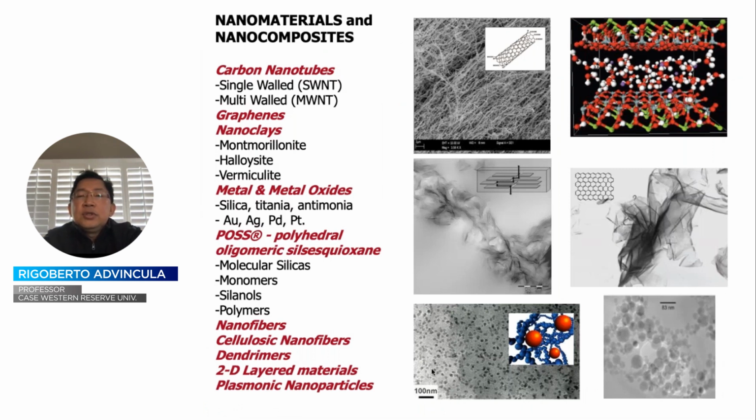So with that, I would like to use the rest of my time to focus on nanomaterials and how we've used this together with SLA 3D printing. Nanomaterials represent an added dimension for controlling the thermomechanical properties by using filler materials. And as you can see here, the nanofiller materials comprise clay, nanoclay, nanofibers, cellulosic nanofibers, and then graphene. A lot of these are commercially available, and many companies are very interested in using these nanofillers to further enhance the properties not only of SLA or DLP printed material, but other techniques such as FDM, SLS, and so on.